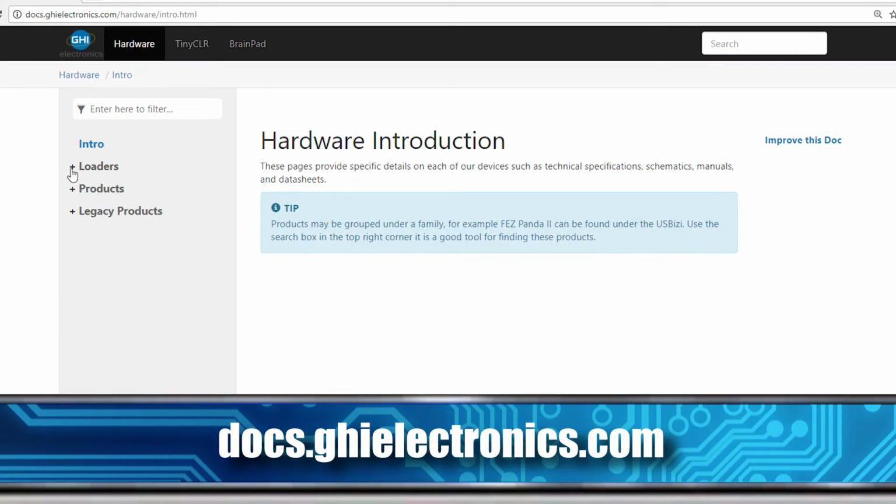Now, we need to load the binary file on any ST chip through DFU. You need to convert the binary to a DFU file. The first step, this is the same steps we always follow. This is explained in our documentation under the STM32 bootloader. So if you want to see the instructions there, I'm going to do it really quick over here.